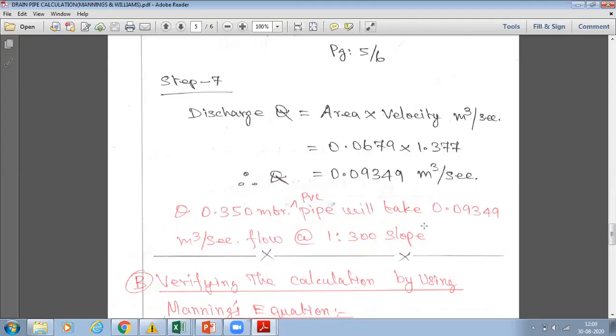In that case, you don't need a separate calculation for the flow rate. You can take the client inputs. The client will give the flow rate for all the equipment. From the equipment flow rate only, you have to calculate the pipe size. For that you can use this Manning formula for the pipe size calculation. So you have to compare the flow rate with their flow rate.